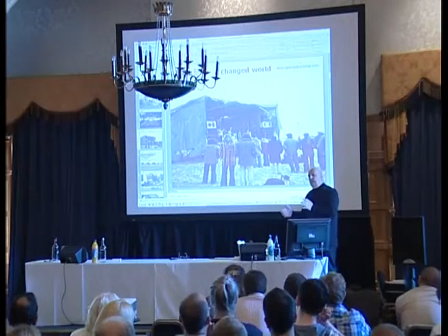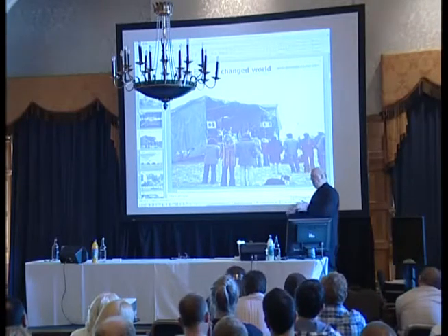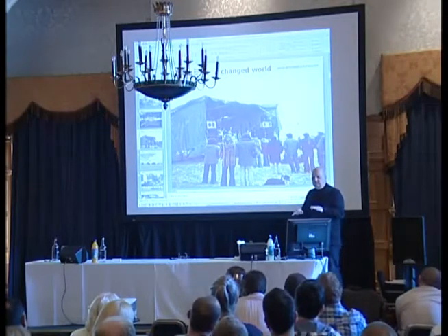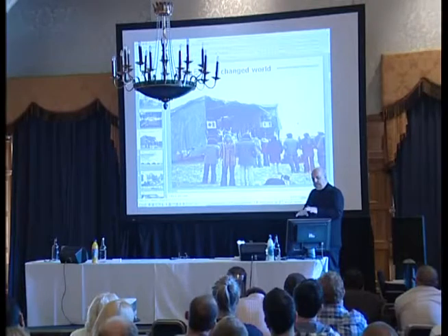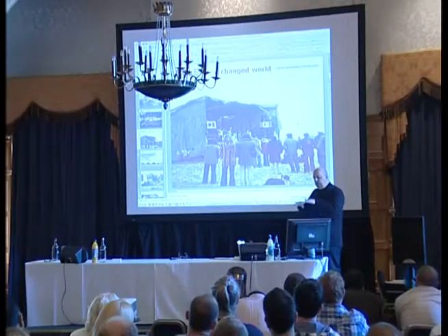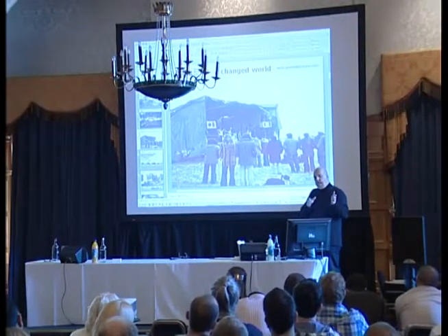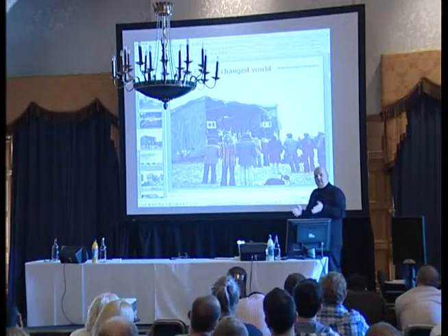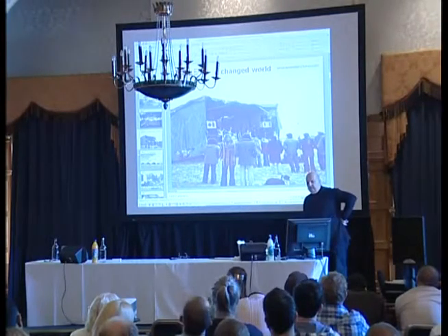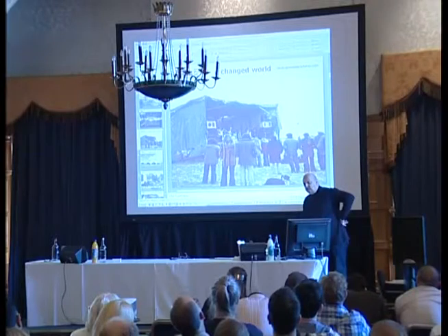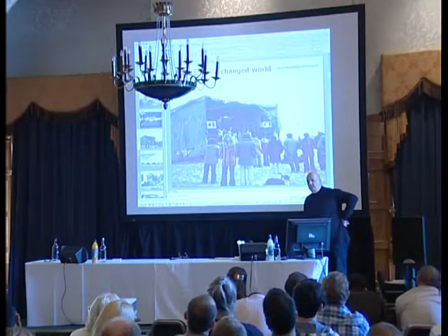you've got this situation where the sheets are sliding into a frame that's already stabilised. With big frame tents, you have the same thing. With big tops and with ground support, even if the masts and everything are guyed down to an adequate amount, for example, ground support stages, there's a point halfway up, even if you do guy the masts, the uprights, where any wind loading on it could actually break the uprights and cause them to fail. You could just shear at the connection or whatever. And whilst it's not dangerous, it is a peak point to be watched during the erection process.